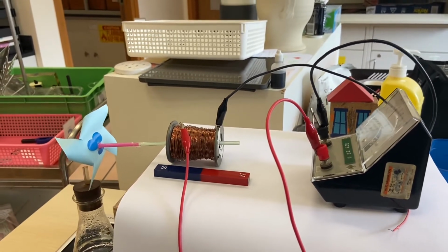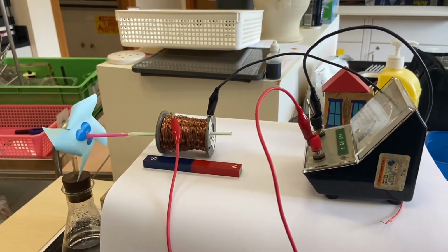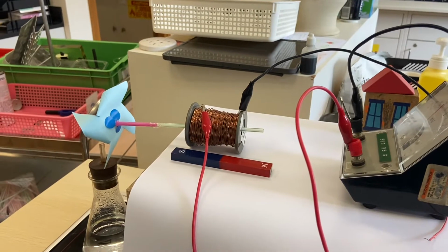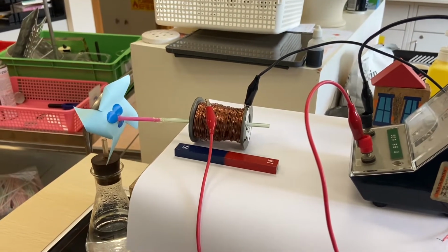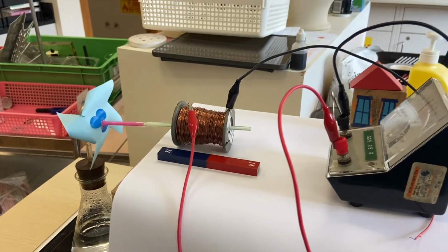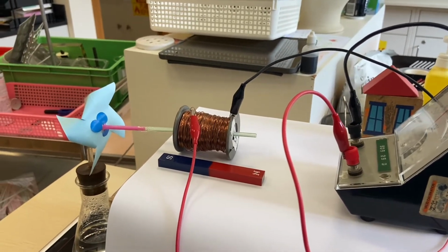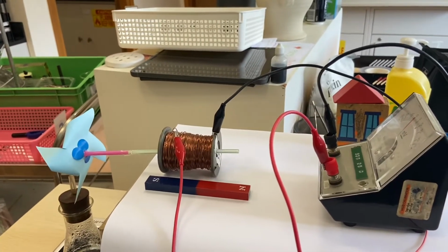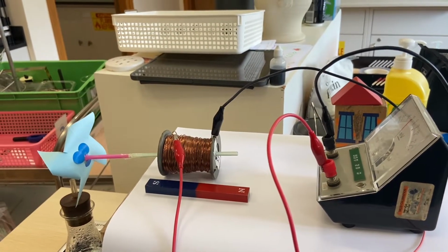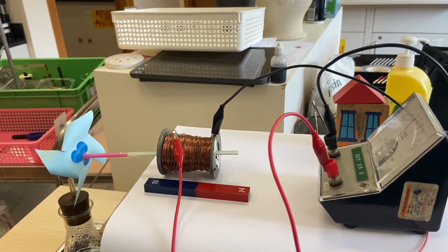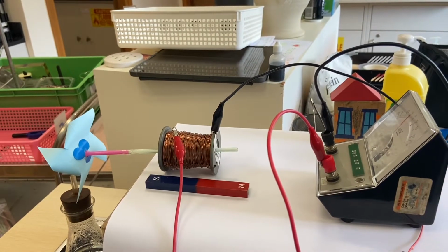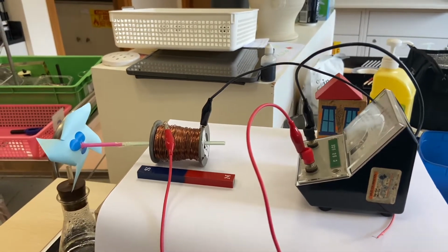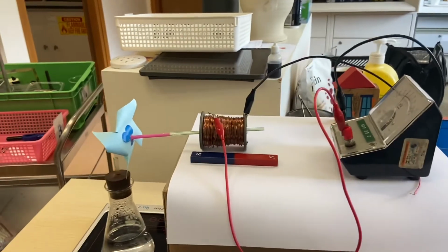Some of the cons of this type of energy are that there are some volatile elements under the ground, such as mercury and arsenic, and some noxious gases. Hydrogen sulfide is a noxious gas that's been produced, and recent technology has looked at ways of trying to eliminate that type of contamination. So scrubbers and abatement technologies have been developed to try and remove those noxious substances while maximizing heat energy output.